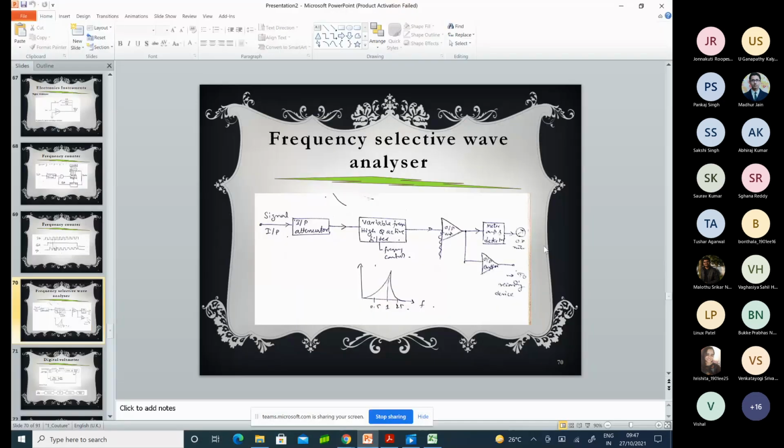So suppose you have a time domain signal, and when you want to represent it in the frequency domain, you have to do the Fourier transform. Now if you have a signal that is not continuous, say a time domain signal that is sampled at some interval, so you have time versus amplitude data in the time domain, when you want to convert this data to the frequency domain, you need to do the discrete Fourier transform.